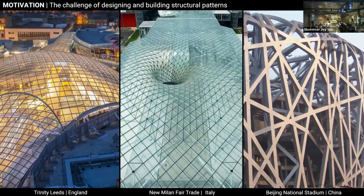And the last one on the right, you can see here you have quite a complex connectivity that's quite variable, with small openings, larger ones, and mostly it lacks hierarchy. And when it comes to structural design, we like to have a hierarchy to understand how things behave, or how we build them from the main elements to the more secondary ones, which ones carry most of the forces, which ones are more for local stability.